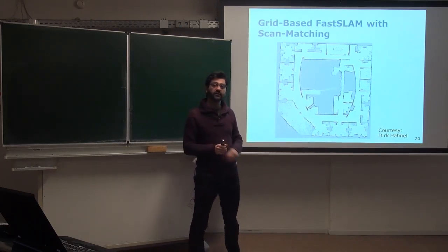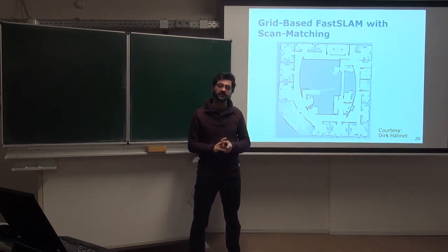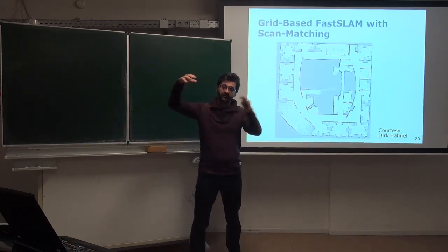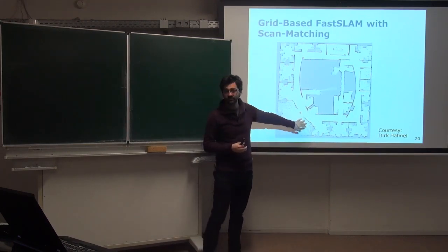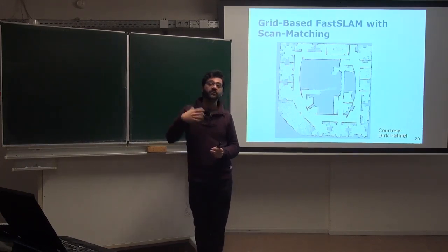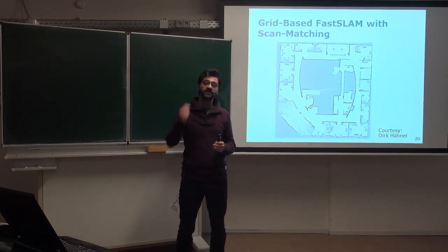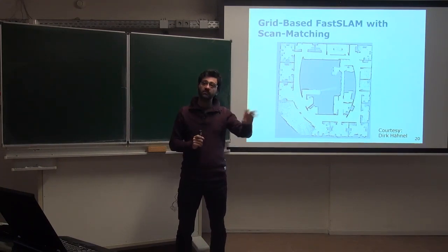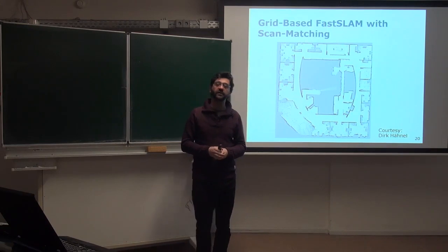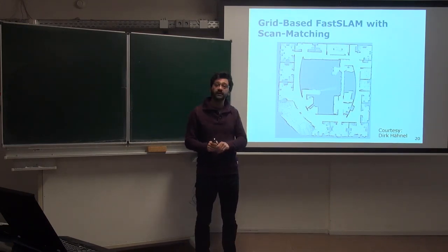There are some tricks for saving memory, in a way similar to what we have seen for FastSLAM in the last lecture, where we had this tree in which different particles, different samples, were storing parts of the landmarks in a tree-based representation. We can do the same with maps. We can divide the map into small patches, and use the same technique as this tree, where instead of storing a single landmark, we store a patch, and we share patches among the different particles, so we get down on memory requirements. There are also some other techniques for saving memory which look similar.